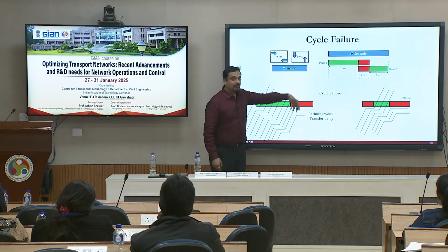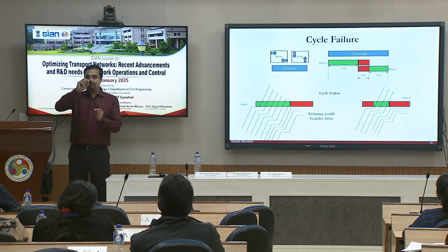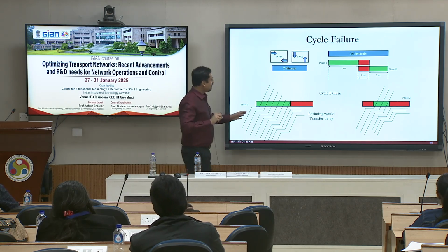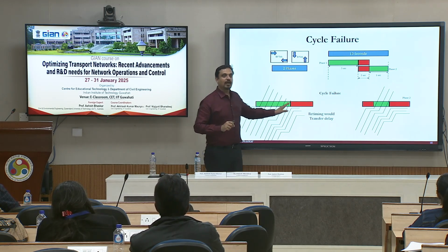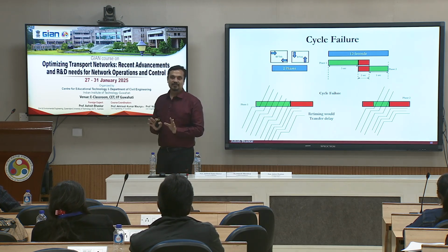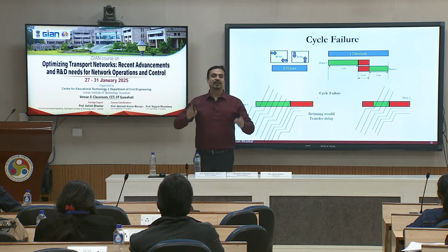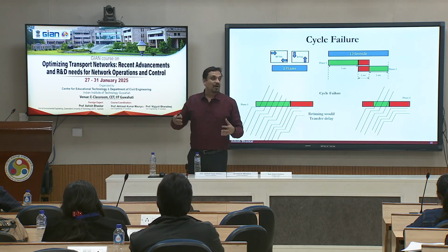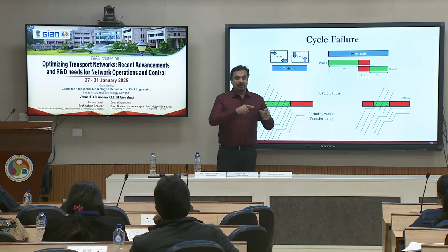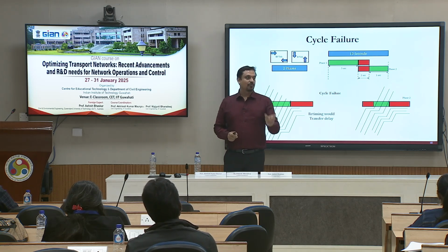If you have detailed detector data, detailed meaning pulse based information, then you can think of looking at your occupancies for the green time and your early red time. That can give you some indicator. But the catch here is you need to have detailed detector data, more of a pulse information based detector, which is giving you detailed information.